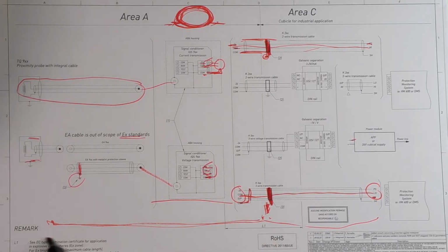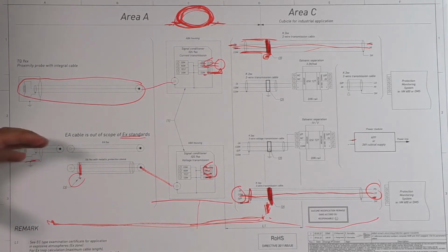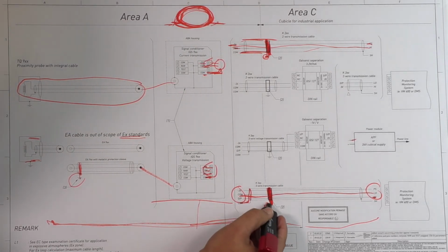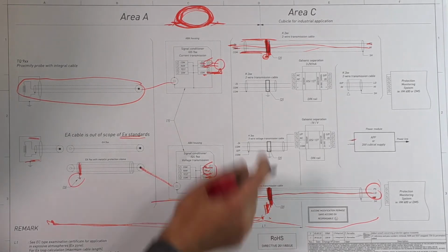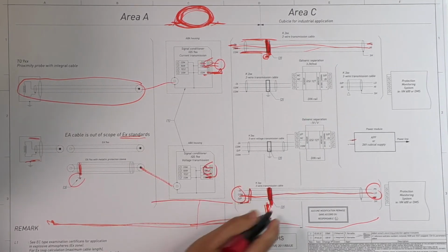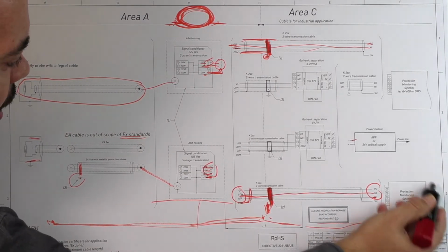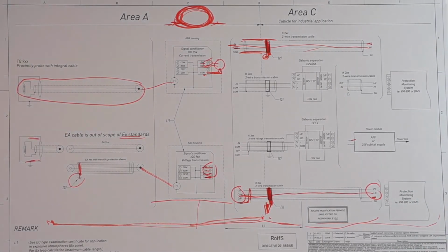They can be very, very long, especially between the conditioner and the cubicle. So you have big antennas. You will be collecting a lot of electromagnetic energy that you don't want, and that entrance is the best way to dissipate these energies, so that they don't affect all the instrumentation that is inside your cubicle.